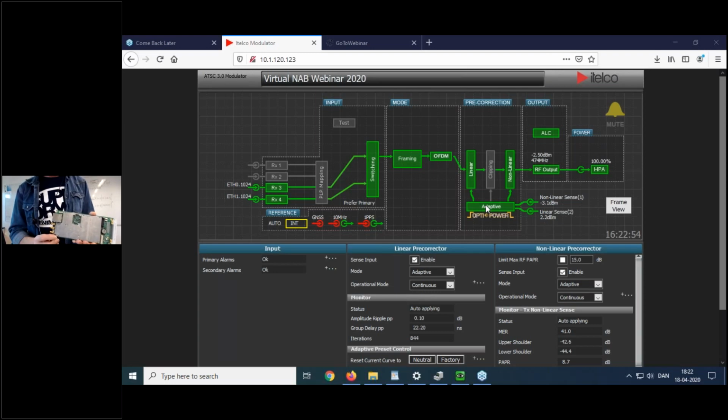When that happens, the transmitter, and in this case that means the exciter, has to switch to a holdover mode so that it continues operating in the right phase and frequency. And the time that a transmitter can operate without external reference and without drifting away so much that it spoils the SFN is determined by the quality of the oscillator. And regretfully, the better the quality, the more costly the device.